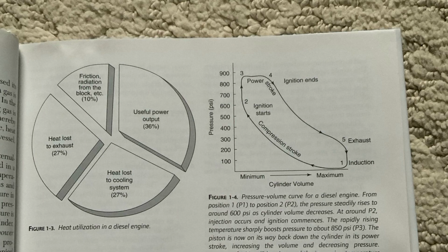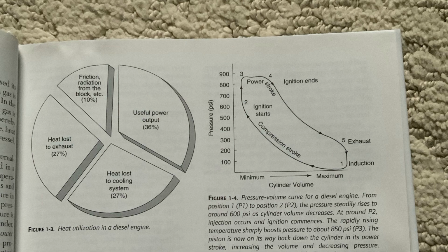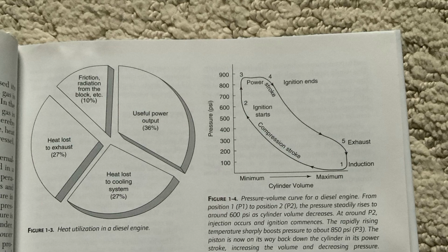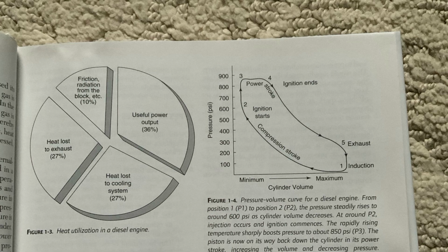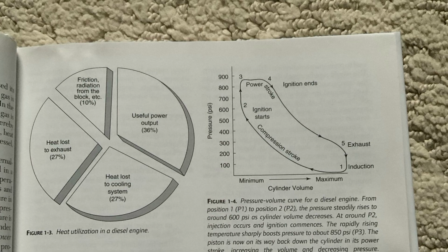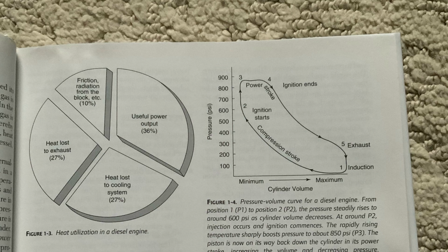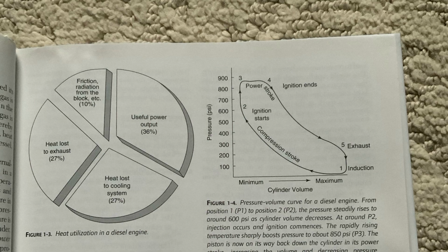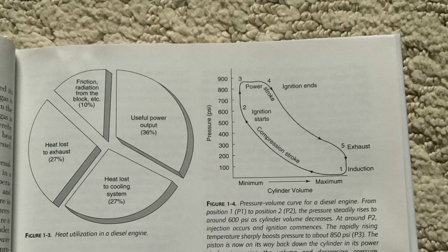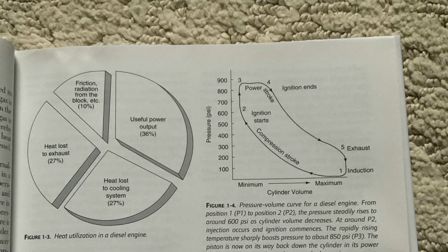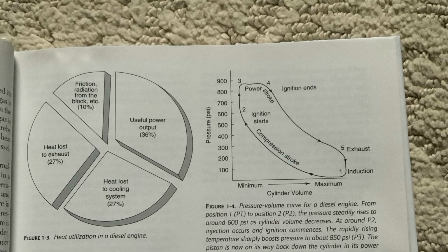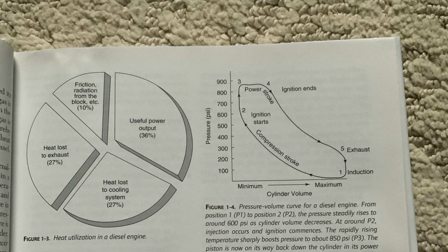When the piston reaches the bottom of its cylinder, the inlet valve closes, trapping the air inside the cylinder. See Figure 1-5. This movement of the piston from the top to the bottom of its cylinder is known as a stroke. It also constitutes one of the 4 cycles of the 4-cycle engine, in this case, the suction, induction, or inlet cycle.